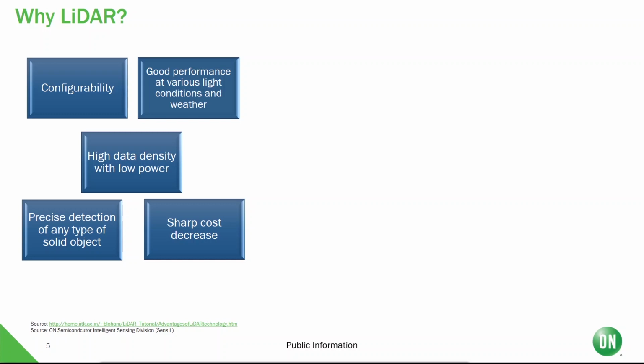Why should we be interested in LiDAR for depth sensing? Well, we can configure a LiDAR in many ways. You'll see scanning, flash, single and multi-point LiDARs, all using the same core principles. LiDAR is robust in the presence of weather and, having its own light source, it can operate in darkness. Precise and detailed images can be built up by combining multiple point range information. Any solid object can be detected accurately, so there's no ambiguity of depth in an image.